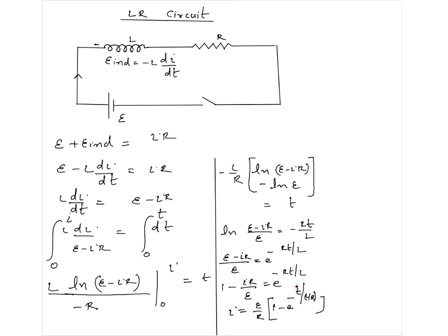So at t equal to 0, you find that current is 0. Now that's very interesting. A battery is there, resistance is there, a closed loop is there, still no current at t equal to 0. And that's thanks to that inductor blocking completely at t equal to 0.